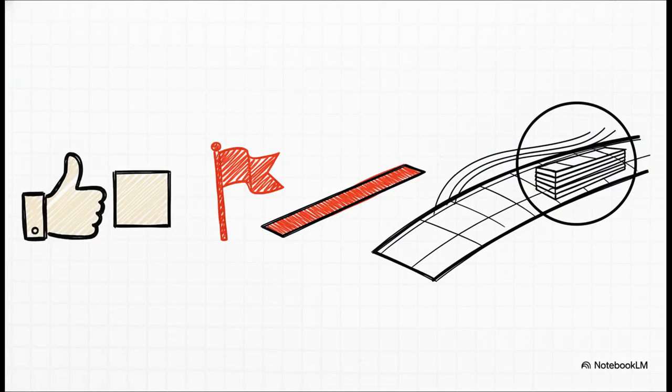So what are the practical rules of thumb? Generally speaking, you want to keep your aspect ratio below 5 to 1. If you see anything creeping above 10, that should be a huge red flag. Now there is one really important exception. In computational fluid dynamics, or CFD, engineers will actually deliberately create high aspect ratio elements right near a surface to build what's called a boundary layer mesh. It's a special case, but a very important one to know about.